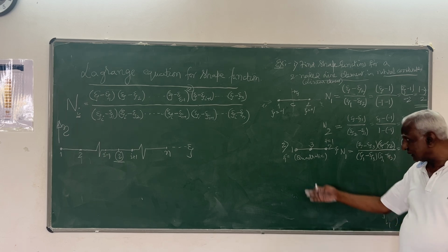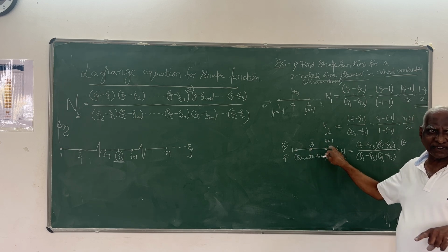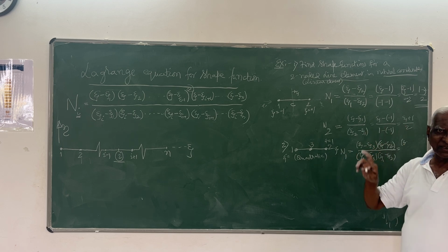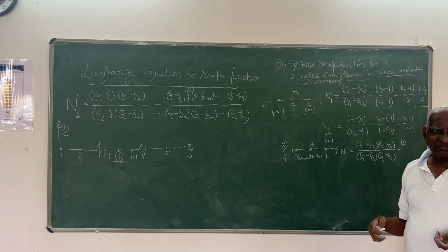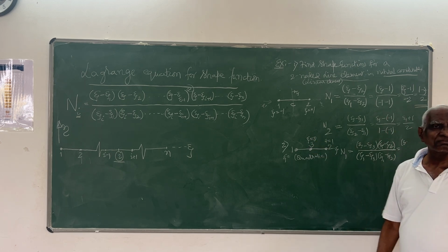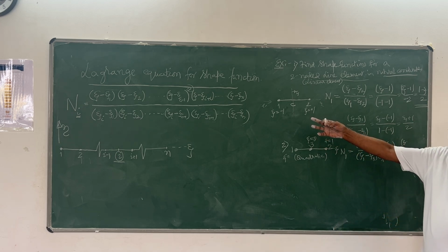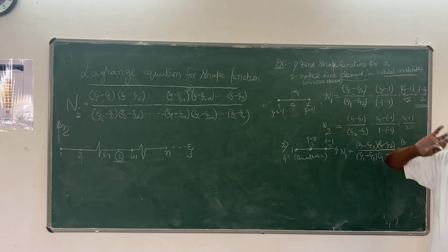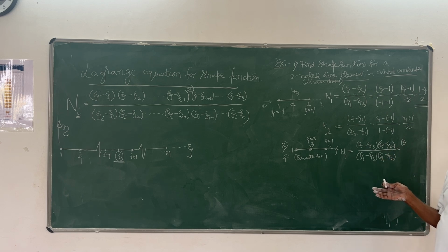Correct? Next I will take one more, cubic. At that time, I will take it at the 1/3 point, 1/3, 1/3, 1/3, middle third. That's all. The node can be placed at any place. This is exactly the center, so that equals 0. That's why this Lagrange shape function is the shortcut method I told you. You can write it easily. So here psi 3 is what? 0.